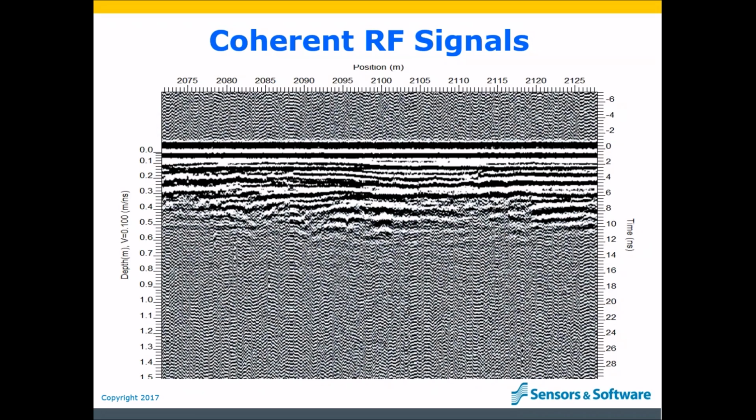In this case, someone in the area of the GPR survey site is transmitting radio signals at a higher frequency, but similar to the GPR antenna frequency. So the GPR data receiver is sampling it as coherent signal. Will high stacking reduce or eliminate this signal? No. High stacking will actually improve the quality of this signal, something we definitely don't want.